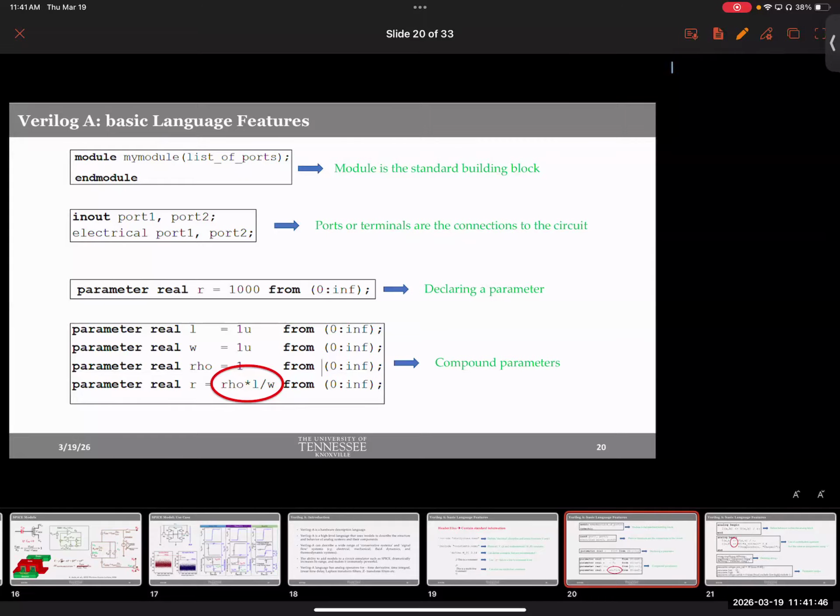All right, then within the module, by the way, everything is within the module and endmodule, you have to define the inputs and outputs, okay? Because the way we view a model is a black box, and it has a set of inputs and a set of outputs, and you have to define those. Why? First of all, when it solves KCL and KVL and tries to look for branch currents, it will get all the inputs and all the outputs and treat them as electrical branches, okay? And there is a reason why I'm mentioning that here, because of the second line. It's coming.